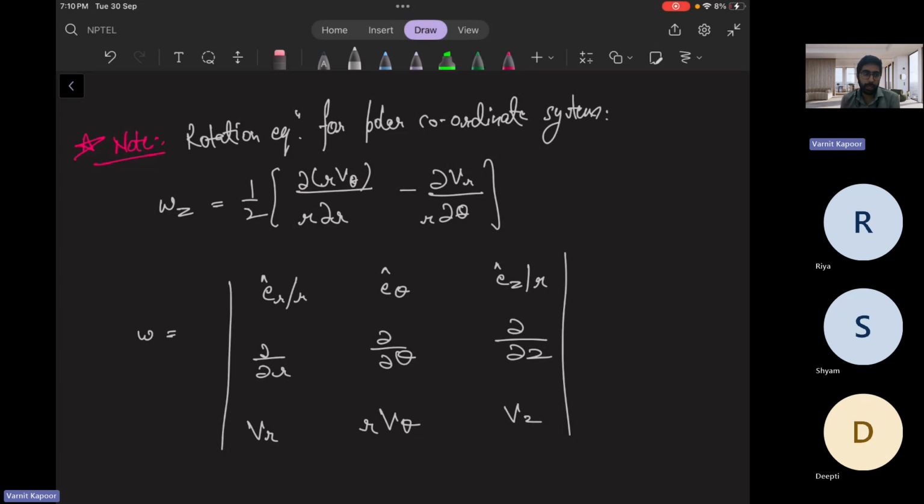That also we have discussed, that when irrotationality comes, that means during the circular motion, the individual fluid particle is not spinning about its own axis, but the whole fluid is moving in the circular motion. But in a rotational vortex, the fluid particle is spinning along its axis as well as moving in the circular motion. Then they can have tangential as well as radial components of the velocities.